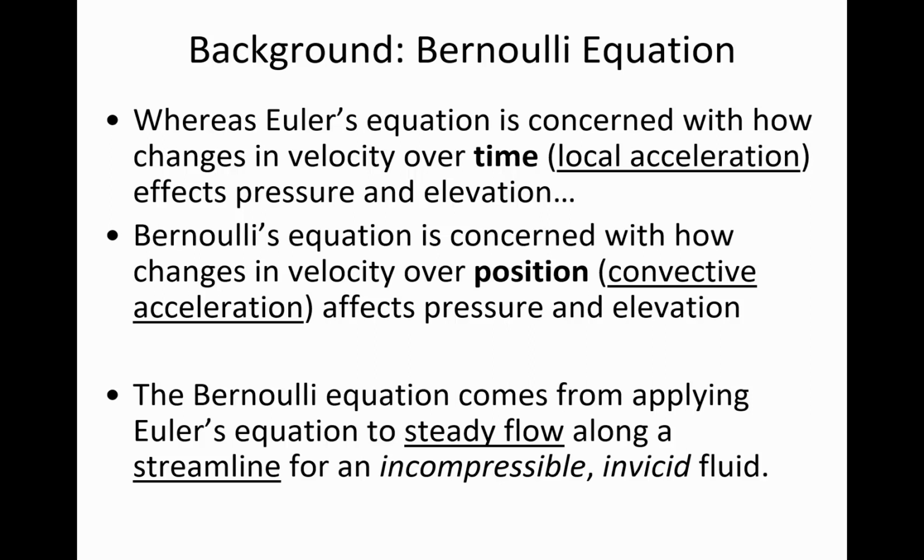And like all the equations we're using this semester, Bernoulli's equation is really just a simplification of reality, and its accuracy depends on how close we apply it to the conditions that are assumed. So for example, steady flow. If you try to use Bernoulli's equation and the flow rate is changing over time, then you won't get accurate results, because Bernoulli's equation assumes that the flow now is the same as the flow later. So the conditions aren't changing with respect to time.